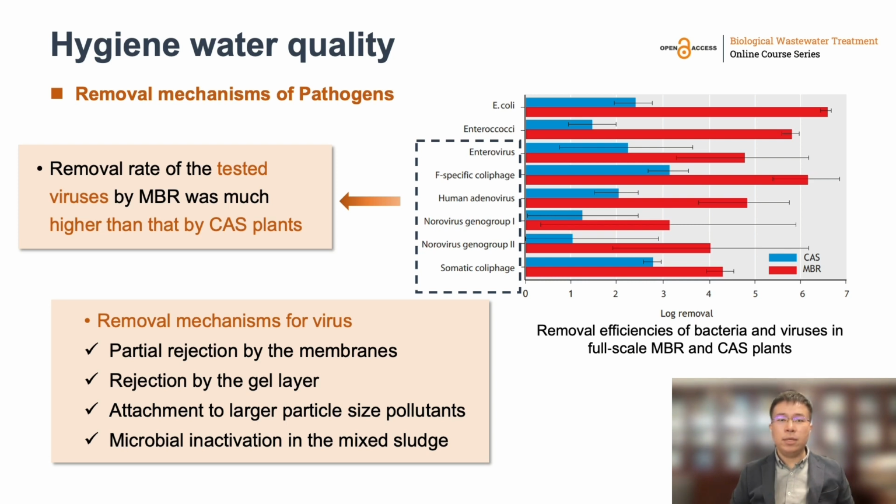A prevailing one is that the membrane and the gel or cake foulant layer together act as a composite filter in tandem to achieve increased rejection of viruses. Firstly, the membrane itself can partly reject viruses, with the rejection rate depending on the pore size. Secondly, the pore channels can be narrowed due to adsorption of effluents onto the pore walls.